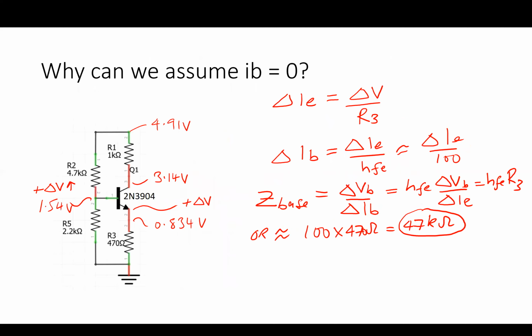So you can see something rather miraculous happening. We have fixed this voltage with a voltage divider that says, I don't care if there is a transistor here. This forward voltage drop is fixed by the physics of the diode, so that fixes the voltage here, which in turn fixes the current through this resistor. Once you fix the current through this resistor, knowing I equals IC, you fix the current through this, and so you now have a stable operating point for this transistor determined by this voltage divider.